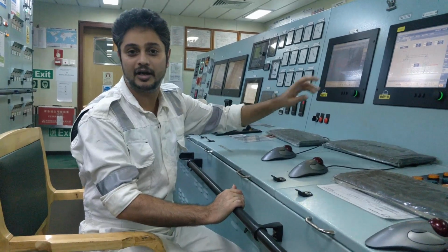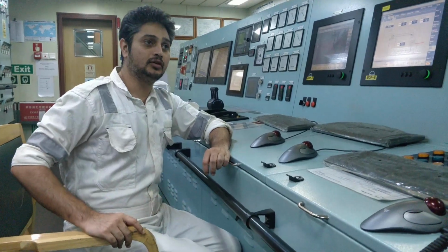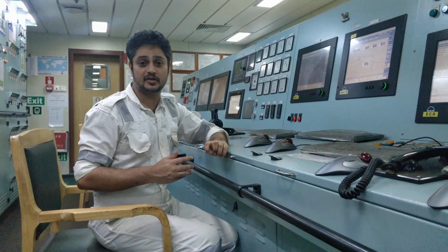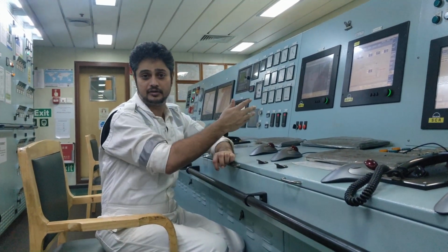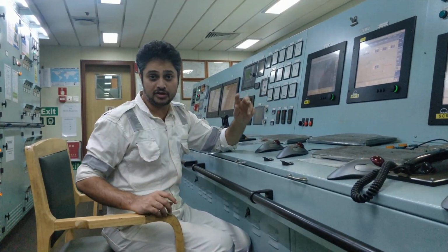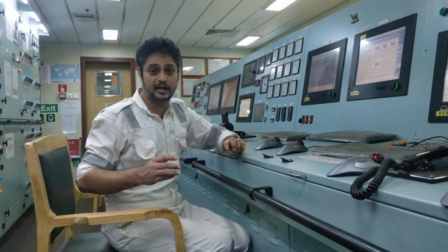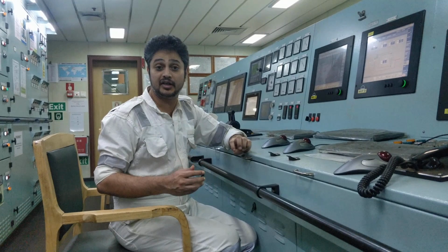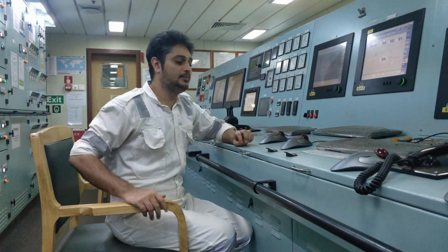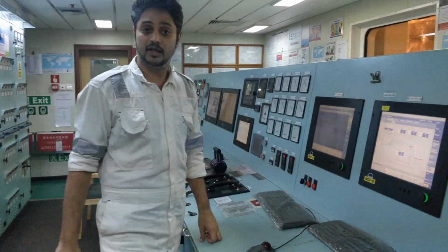This is as per the command given by the ACU. If you see the electronic part, the signal transmission is happening, and in the mechanical part, accordingly as per the signal, the stroke variation changes. In the HPS system also, you need variation in the signal. It is an analog signal, because the HPS pressure will vary according to the engine load and the engine direction.